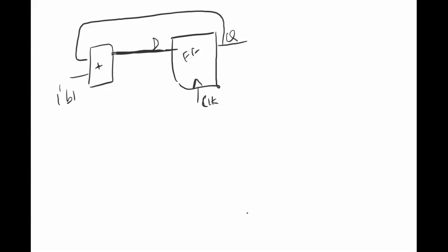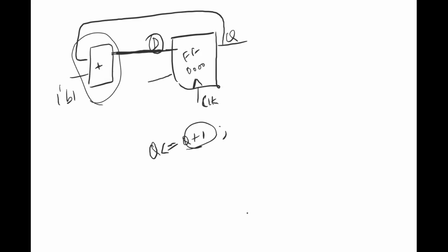So ideally, you will have a stop signal that goes into your design in general, or a reset signal that will push your flip flop into 0000 state every time you hit that particular signal or something like that. So you need not actually worry about the D part, because essentially your main function would be Q is equal to Q plus 1. So this Q plus 1 part is being taken care of by this particular module, and the non-blocking assignment of this will be taken care of by this flip-flop. Does that make sense? Does that help?